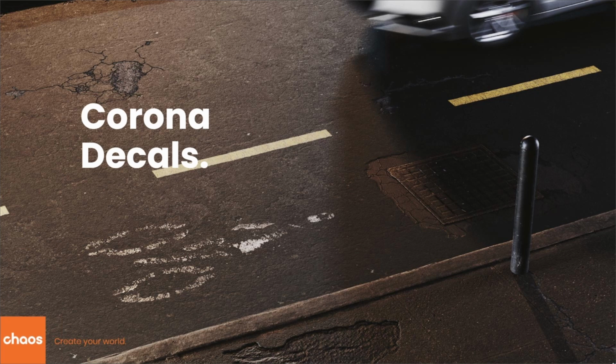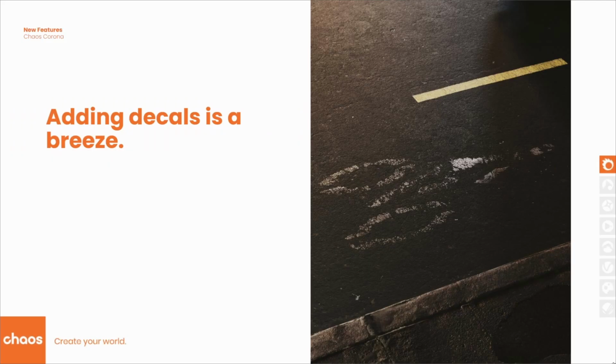Corona decal functionality. This is one of the crowd favorites. And what Corona decals do is they make adding decals a breeze. You can add decals such as, for example, the road markings you see on the image on the right here. You can add decals like that to your objects really simply just by pointing a Corona decal to your object. And that's it. You don't have to mess with UV mapping or any kind of layered material with carefully placed masks ordeal or anything like that.